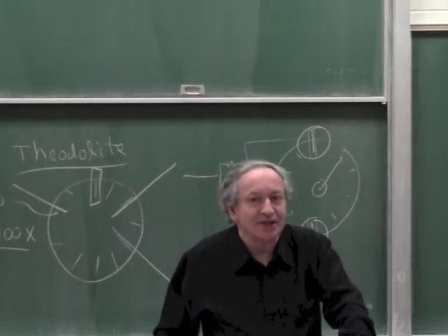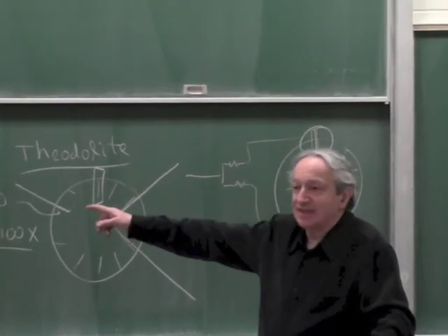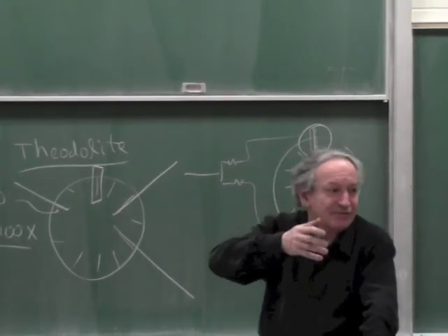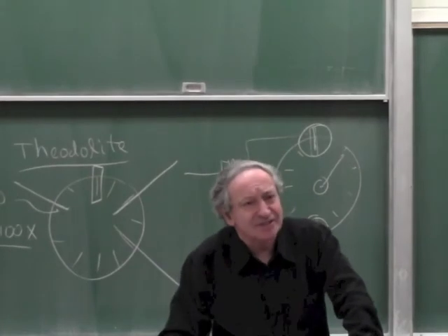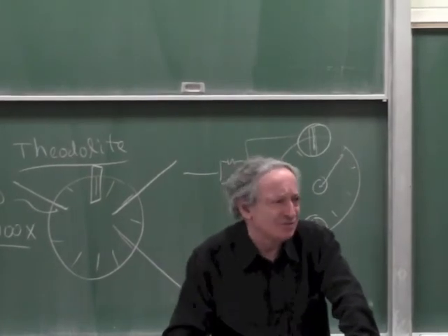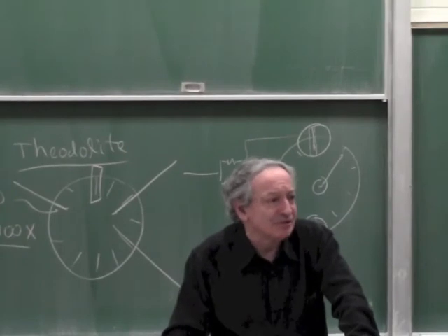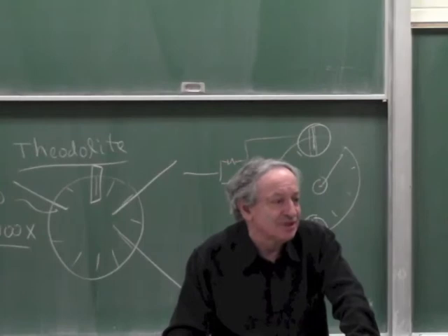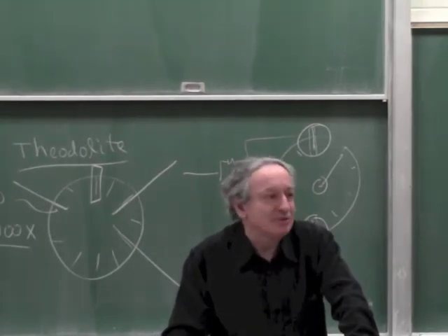Correct, although the lens of the camera has a slight distortion. The camera itself doesn't, because it's made on a lithographic machine. It's deadly accurate, but the lens... But the distortion of lenses is very small. It's easy to get a lens which is 0.1% or even 0.01% distortion. And it's always the same, so you can take it out with a lookup table.